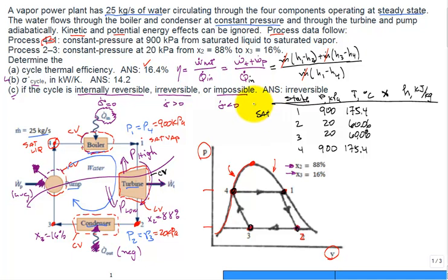I'd like to put a little note to myself right over here. Saturated vapor. Well, you can treat it like a quality of 1, because you just need that h, or just look up hg. The hg at that pressure comes in at 2773.90. Hey, what table did we use? Well, we've tested you over tables and being able to look up properties, but this would be out of table A3 as a little reminder. Go to table A3, get the enthalpy for saturated vapor at 900 kilopascal.